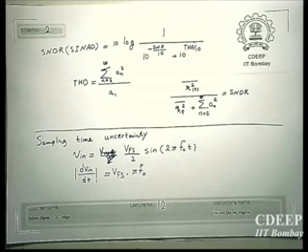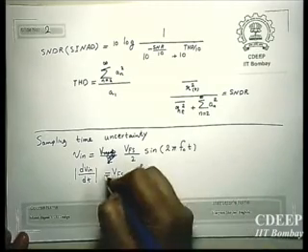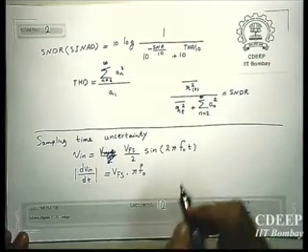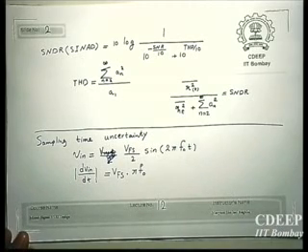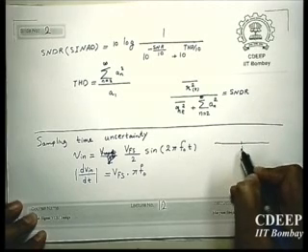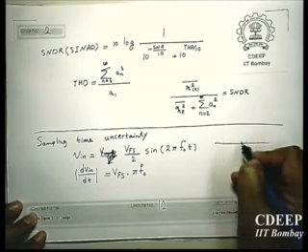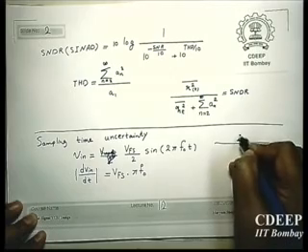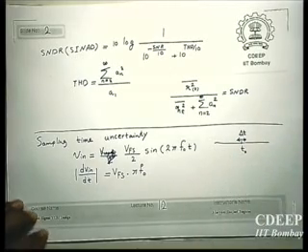Now, if the sampling time has some uncertainty, one part is the switch effect and one is jitter in the sampling clock, that definitely gives you uncertainty. You cannot say that this signal has been sampled at this particular time t0. Definitely there will be some uncertainty associated with it.